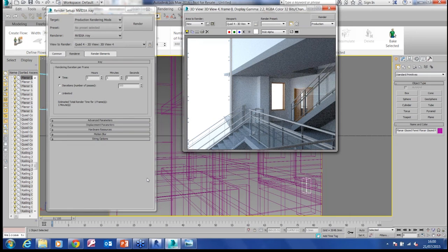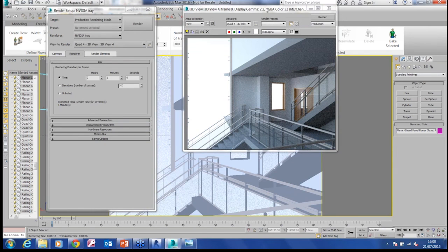We've also got the ability to set up a render farm using 3ds Max. So if you've got plenty of high-powered machines that do nothing on an evening because everyone goes home, you can utilize them to do your renders. And we've got a lot of people out there that do set up render farms so that they can set their high-end renders up on an evening, and they're finished by the time they get in the morning.